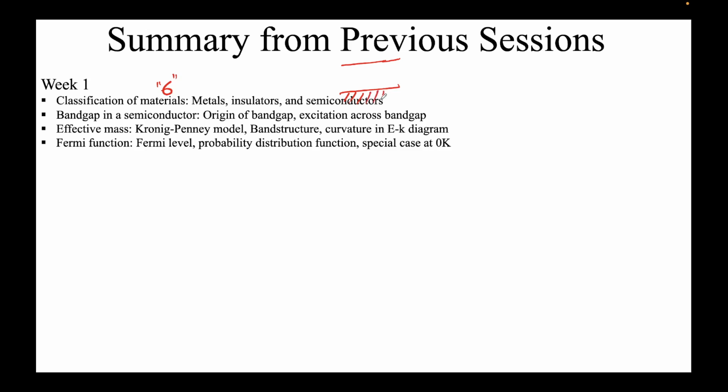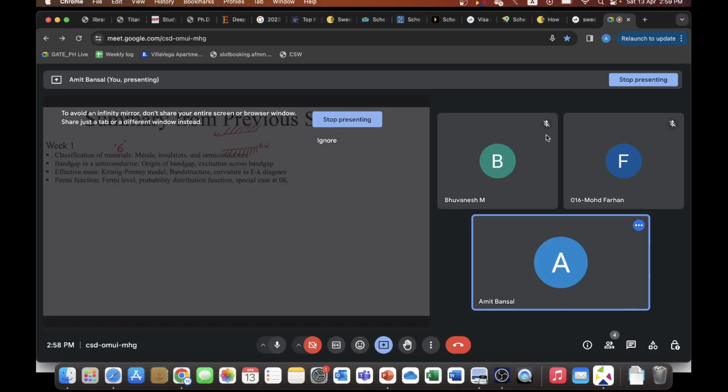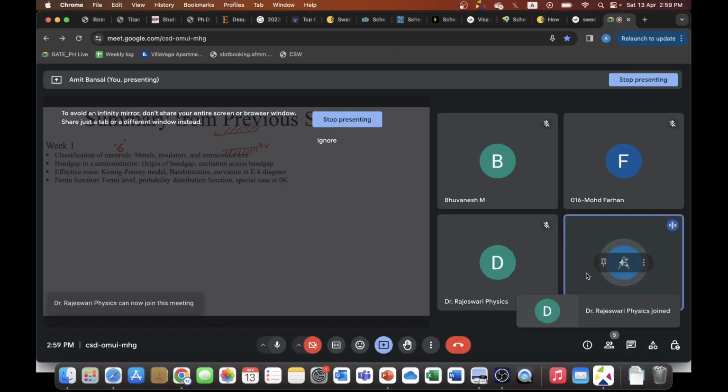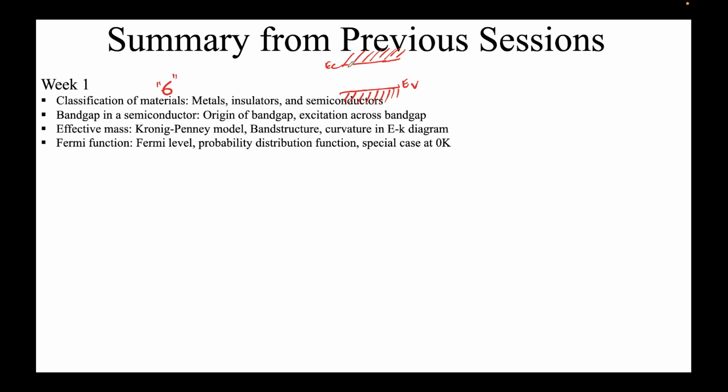So this is the lower energy band, which is filled up to this energy level, we call it EV, and there is another energy band above, EC, which can also be filled. But between EC and EV is something which is not allowed. Hence this is also known as the energy gap or the forbidden gap, right? Electrons can reside below EV or above EC, right?